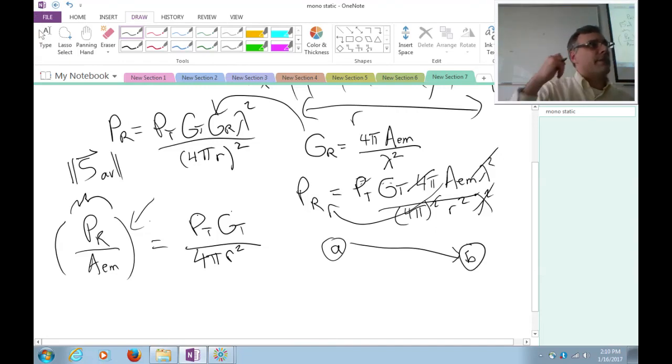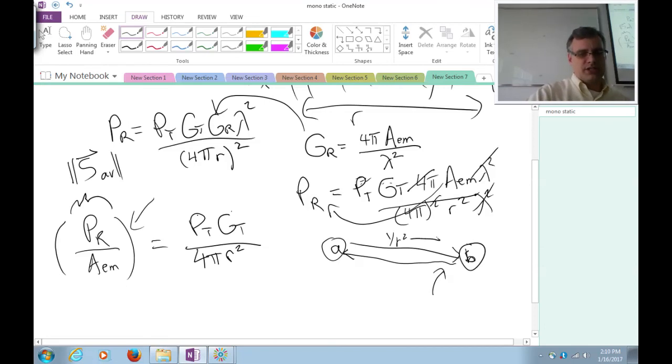So if you think about it, a radar link, especially this monostatic one I'm drawing here, you can think of it as an antenna here, B at point B, that almost has two link budgets glued together. That antenna absorbs power and then reflects it back. This should have 1 over r squared losses this way. This should have the same 1 over r squared losses in the other direction. The area over which I gather and then re-radiate power is this thing called radar cross-section, sigma RCS.